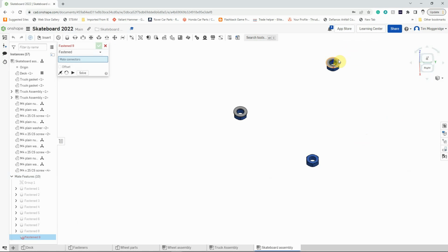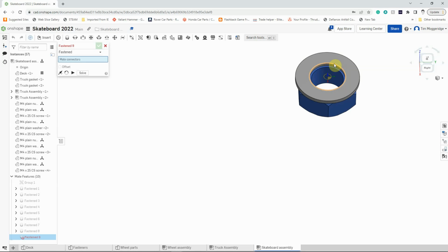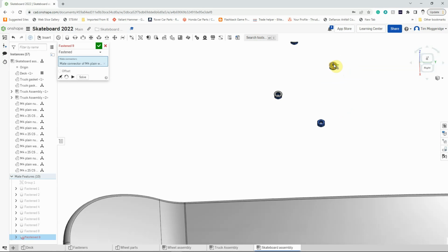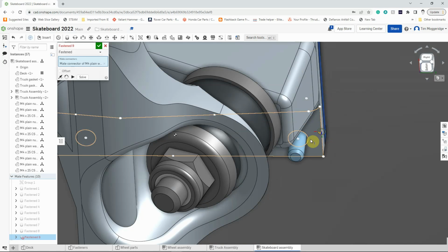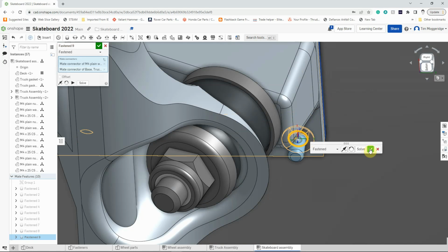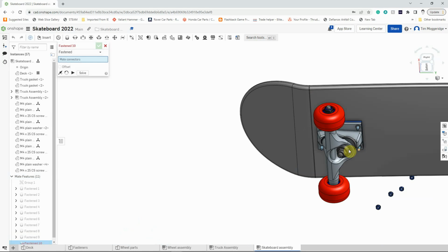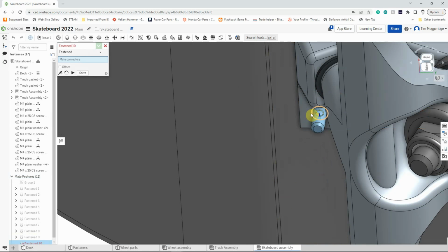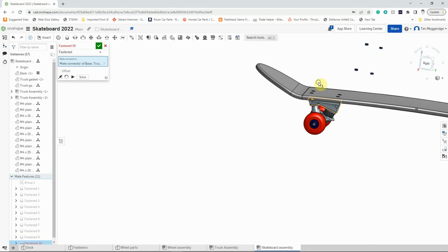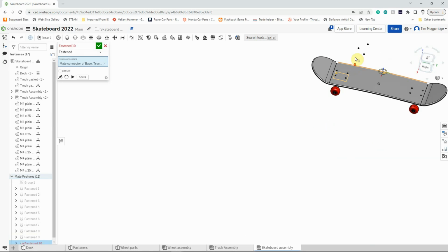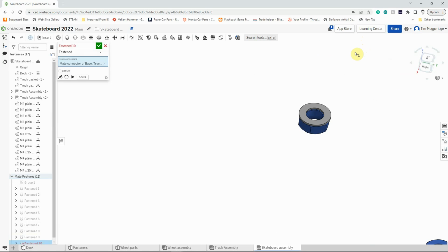with the next washer. So just zoom in to make sure we've got the right edge, zoom out, zoom in, pick the right edge, click to confirm, do it the other way around this time, pick the edge, so that's the edge of the hole, zoom in again, top edge of the washer.